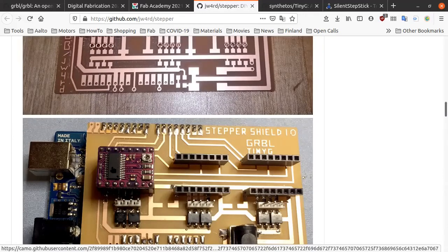So these chips, they are different in size and shape, but the actual functionality of those is quite similar. So usually you just need to give it a pulse in order to drive a motor one step forward. But if you make it in the form of a step stick, these are easily replaceable. So you could, let's say, try out 5 different step sticks and find the one that fits best for your design.